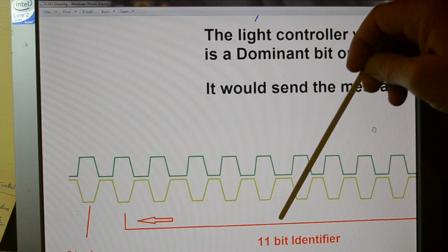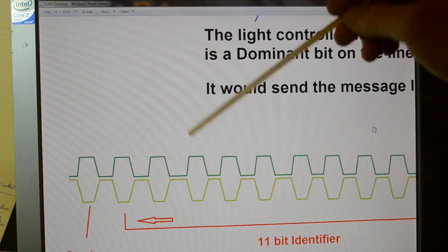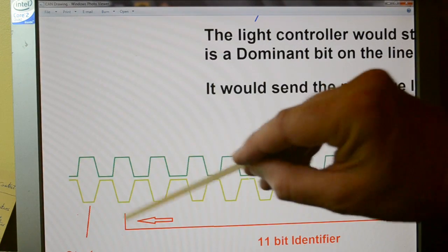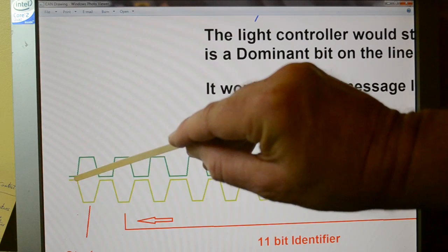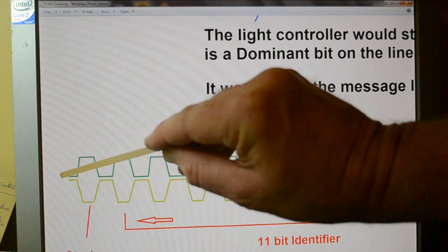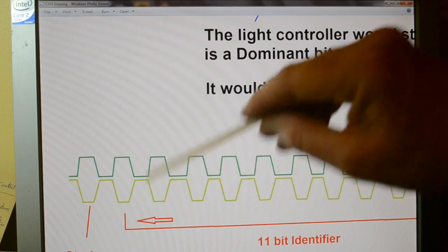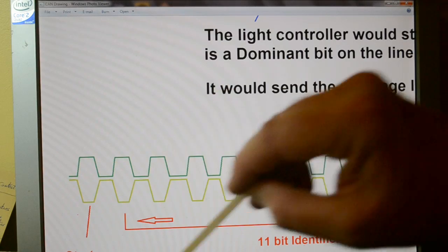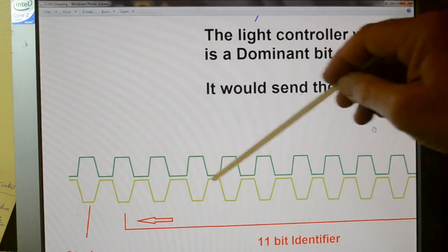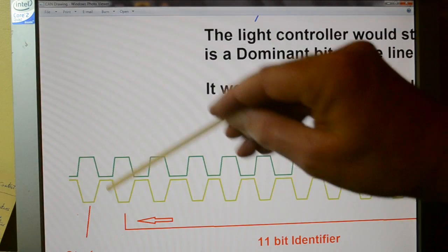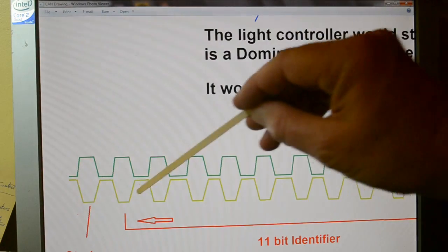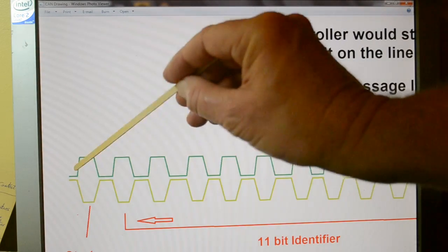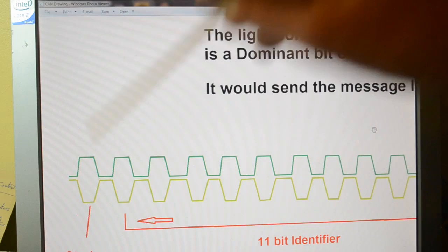So today I'm using the 11-bit identifier example. That's what I programmed on the microcontroller, and I can show you all this on the scope. So we've got a start bit, and with this start bit, on every transition from 1 to 0, the receiving node will adjust its clock and synchronize on these leading edges. So we're only transmitting the data, and each node has its internal clock, which synchronizes here. I'm not sure if it does it on every edge or every 5th edge, but it certainly synchronizes on these edges, certainly at the start bit.